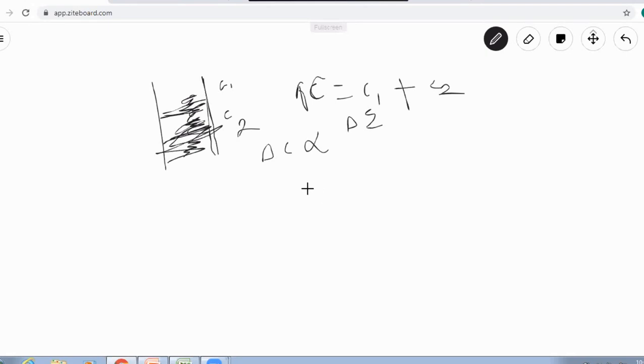Now if we see this equation, C equals epsilon A by D. What is the output now? The change in capacitance. What is the input now? The change in distance, the third measurement. So what will be the sensitivity in that case? We can get it from dC by dD.